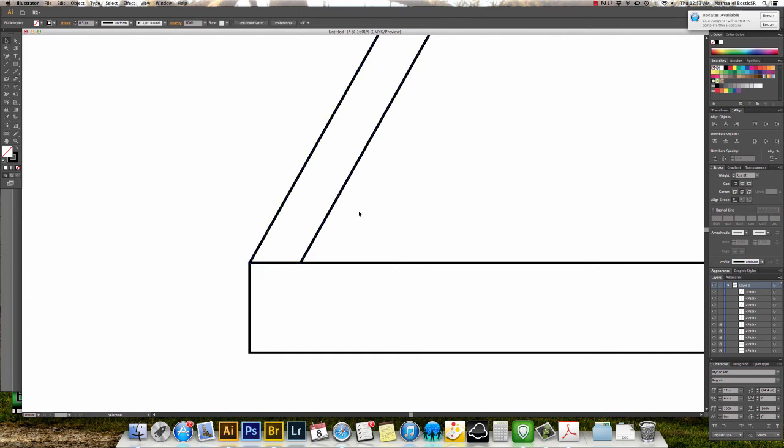So there you go. Alright, so when I was looking at my stroke, I originally saw just this. If you put your cursor on the name of that panel and you double click, it toggles you through the different views of that panel. So just go to where you can see your corner and change it to round join if you want.